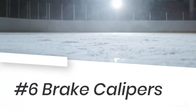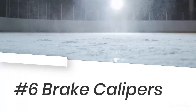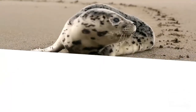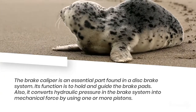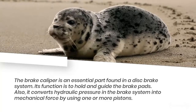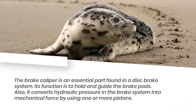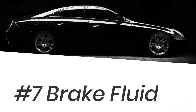Number 6. Brake calipers. The brake caliper is an essential part found in a disc brake system. Its function is to hold and guide the brake pads. Also, it converts hydraulic pressure in the brake system into mechanical force by using one or more pistons.